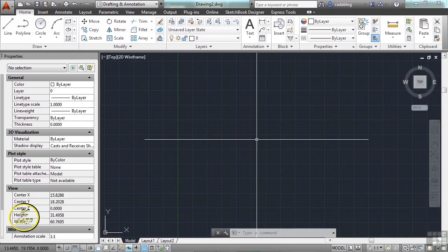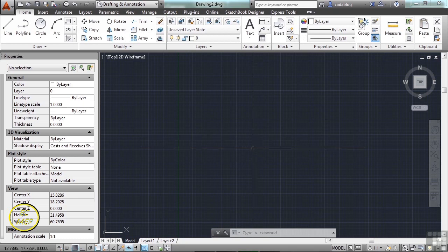There are many ways to create blocks in AutoCAD. Any drawing can be even used as a block, so you can start a new file and draw a block there. Later, you can insert that file with the insert command. Now it's a block in your drawing. Or you can combine objects in your current file to make a block inside it. Then you can export that as a block or as a file to be used later on.